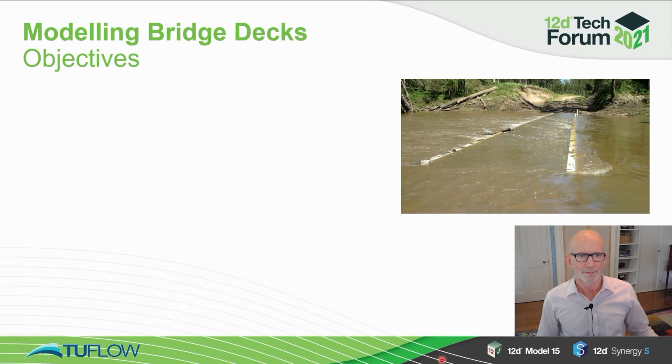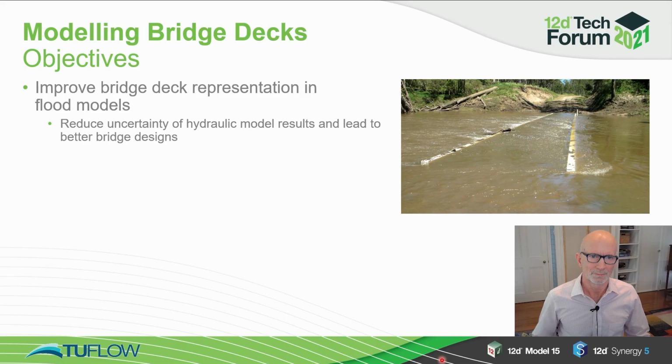The other little topic I'm going to mention before we wrap up is that modelling of bridge decks has always been somewhat problematic. Main Roads in Queensland, Transport Main Roads, have been working with us to try to improve how we represent bridge decks. Bridge piers we're reasonably comfortable with. When it comes to bridge decks, there's still a fair bit of uncertainty about the parameters we should push into these models. The reality is that it's quite a complex flow going on around the bridge deck. You've got water surcharging on this side. It's certainly not one-dimensional, it's certainly 2D, and there are even 3D effects in the vertical.